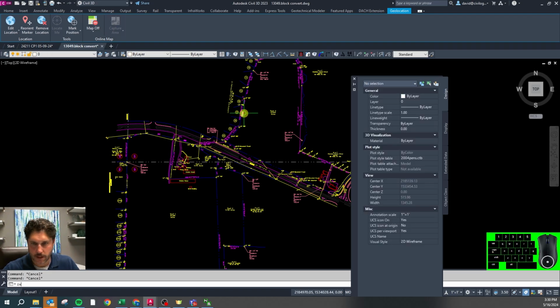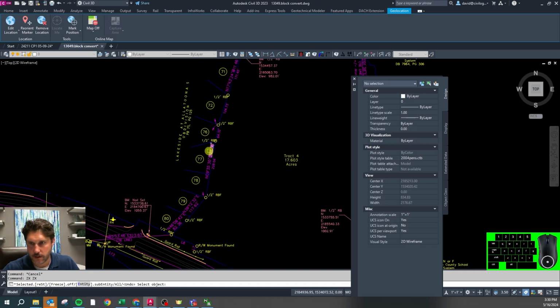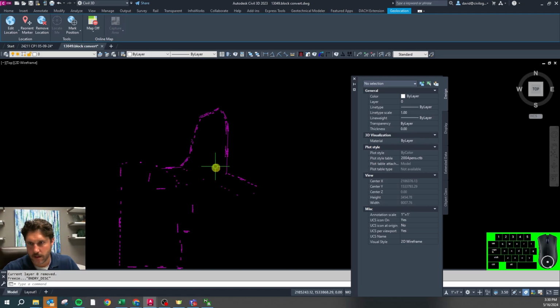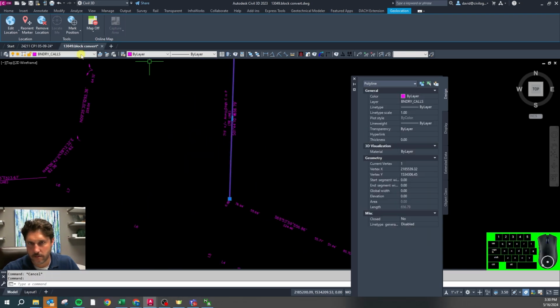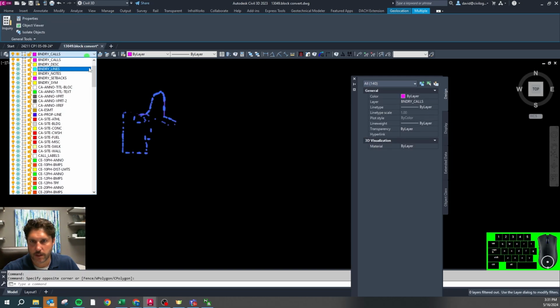We'll use the ZX command, and you can see down here it can either turn off the selected or turn off rest. Right now it's on rest, so it's going to turn off the rest of the stuff other than the items that I click. Then I can run the command again and pick these two things, and then run the command again and pick that thing. This looks a little weird. We'll check into that in a few minutes.